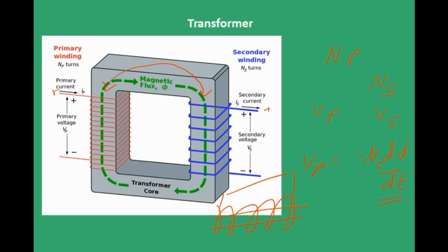Say here you have input voltage, and I want a second coil on the same rod with different number of turns, of course, and here I can have output voltage. Yes, this also works. The concept is you should have a same magnetic flux linkage, and this is possible either by using this arrangement, or you can wind both the coils on the same rod as well.